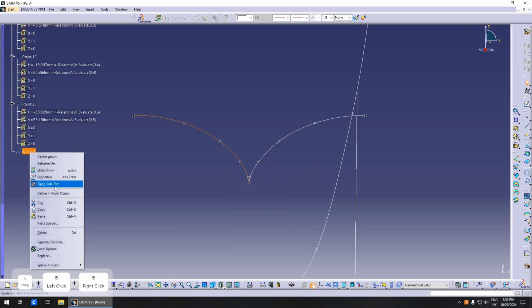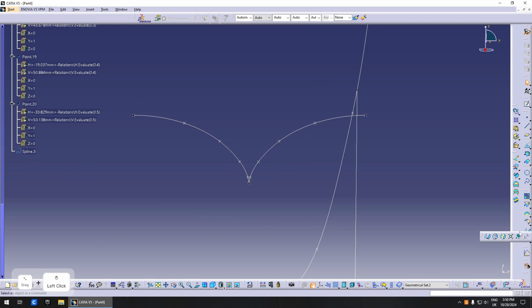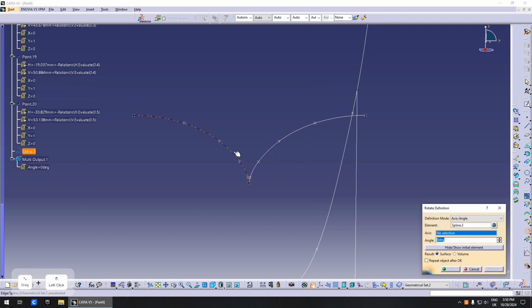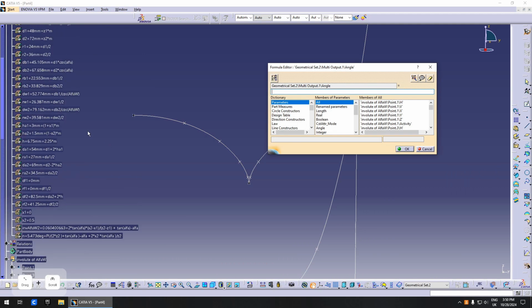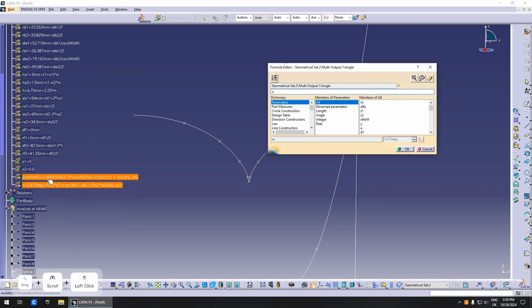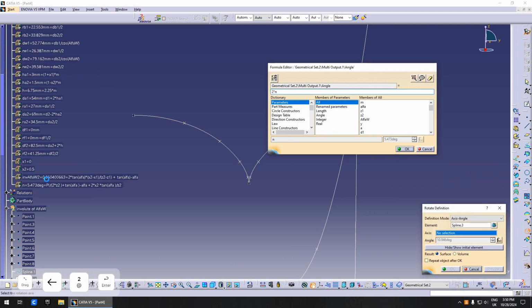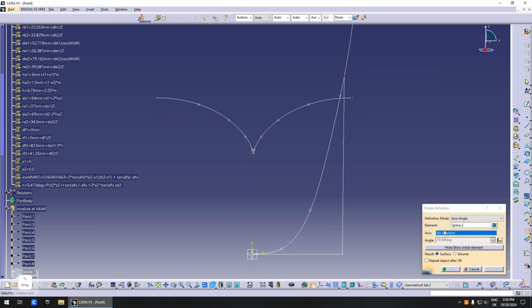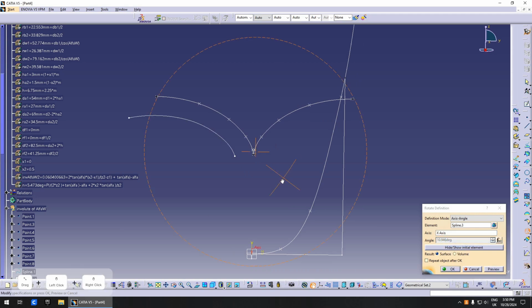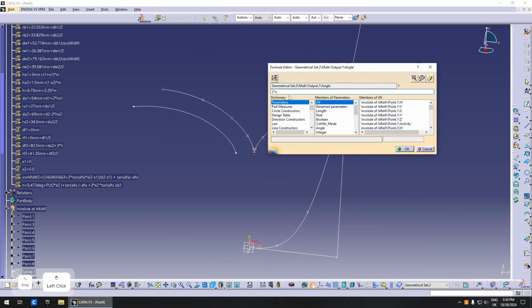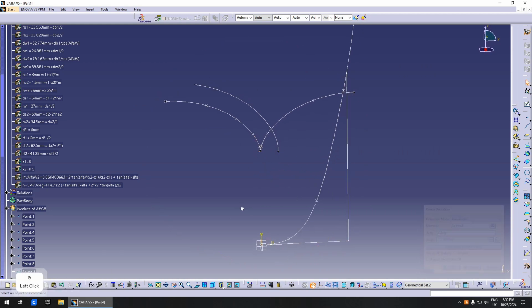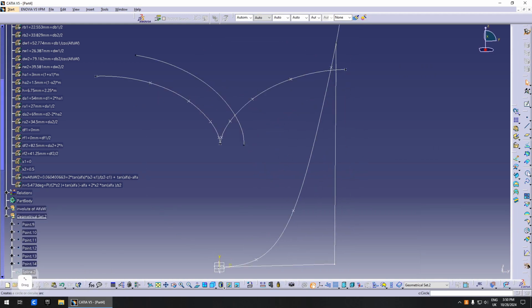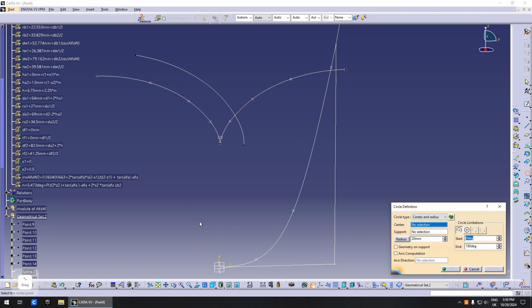Now what you need to do is rotate this around. So there is this rotate. You rotate this. The angle is this parameter that you just added. This is a half angle, so I guess it's 2 times this. The axis is x-axis, and the direction is wrong, so it needs to be minus. So we have what looks like our first tooth.